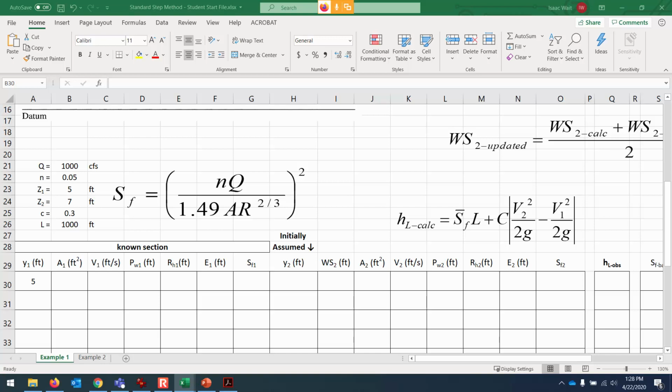depth of 5 feet, and then the side area as well of the triangle will be 5 times 10. So we're just getting the area of the trapezoid here. So it is 25, because that's the channel width at the bottom, times the depth, plus the depth times 2 times the depth.